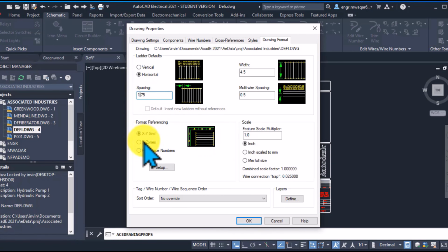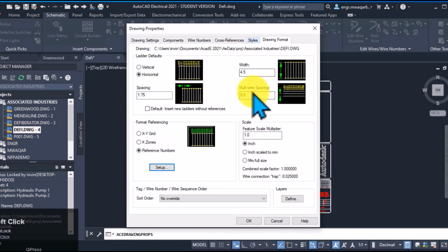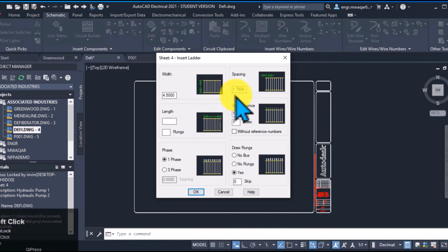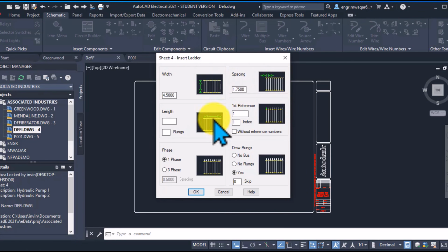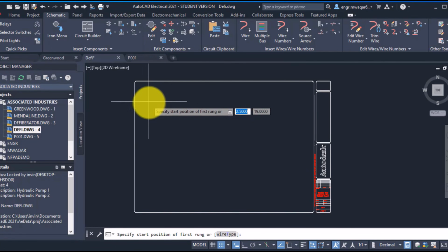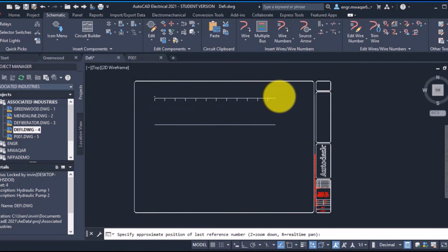That is wild. Why wouldn't it show it? Because you have to explicitly check a tiny separate box in a different menu that says Insert XY Grid Labels. So if you don't check that specific box, you are flying completely blind. You are. You start placing components, and the software is automatically naming them based on a grid that you literally cannot see. You drop a relay somewhere in the middle of the page, and it automatically names itself CRB4. And you're sitting there thinking, where on earth did B4 come from? Exactly. It came from the invisible grid that you forgot to label.